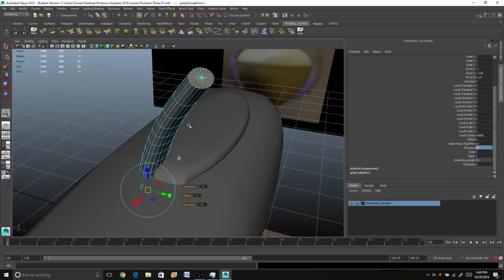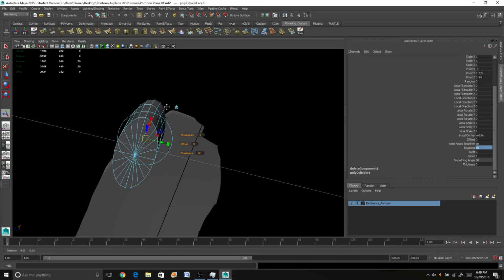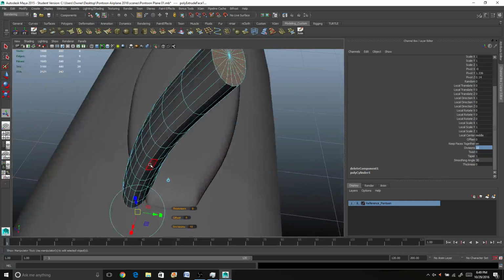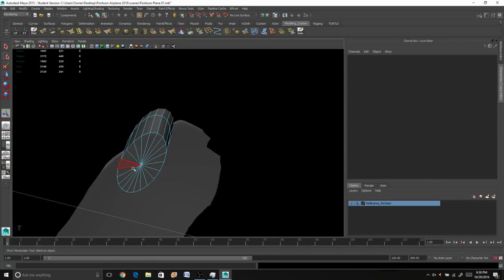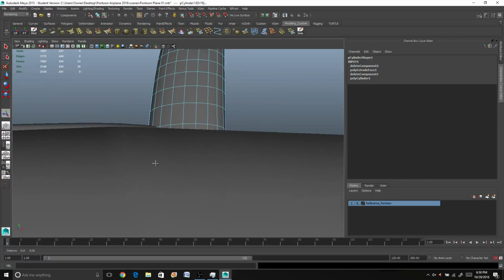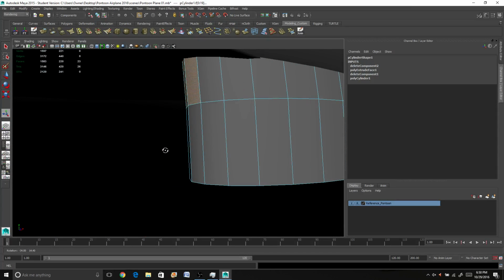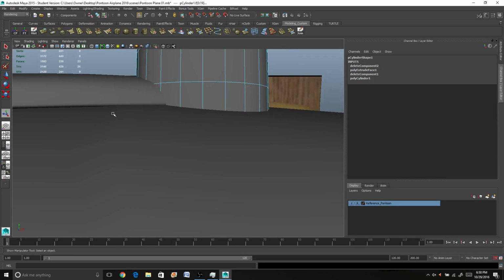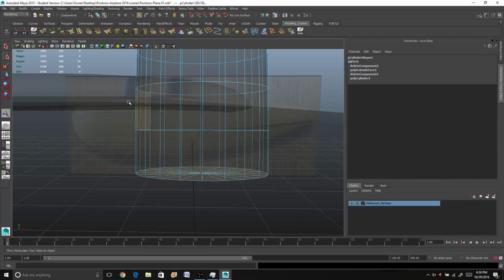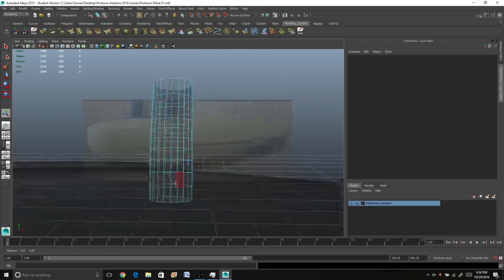So we're going to delete off this cap, and as long as this cap down here is selected, which it isn't, so I'll just delete the top cap first. I'll hit delete, and then I will select the bottom faces down here. Now I can see that I accidentally grabbed something I didn't want. All I have to do is just deselect them. So I'll turn on my X-ray mode so I can see. Hold down Control, left mouse button drag. Now this is a deselection mode, so I can deselect the selected faces I don't want while keeping the other ones. There we go. And I can hit delete. Now that bottom cap is gone. Okay.